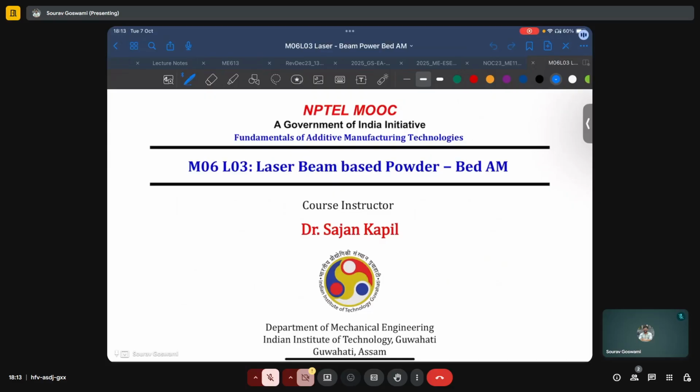Of course, it is very difficult to have a single model which can capture all the physics or address all concerns related to the additive process. For instance, only thermal models or heat conduction based models of the additive process or welding are very frequently encountered, and they are typically leveraged to predict residual stresses and distortions in parts, or to check for melt pool geometries, bead width, bead depth, and bead size.